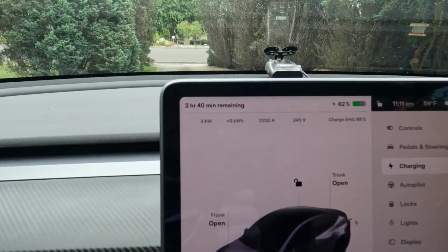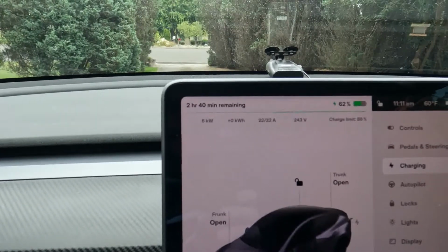Now, why is that a big deal? Well, I'm connected to a 50 amp outlet, but again, it's a smart extension cord, so it's not going to run that outlet at 100% capacity for the entire time because that would make it overheat. So it derates itself a little bit down to 32 amps. That way it's nice and cool, it can operate continuously, and we have no issues. So a 50 amp NEMA 14-50 outlet will give you, depending on how you have everything connected, about 32 amps.